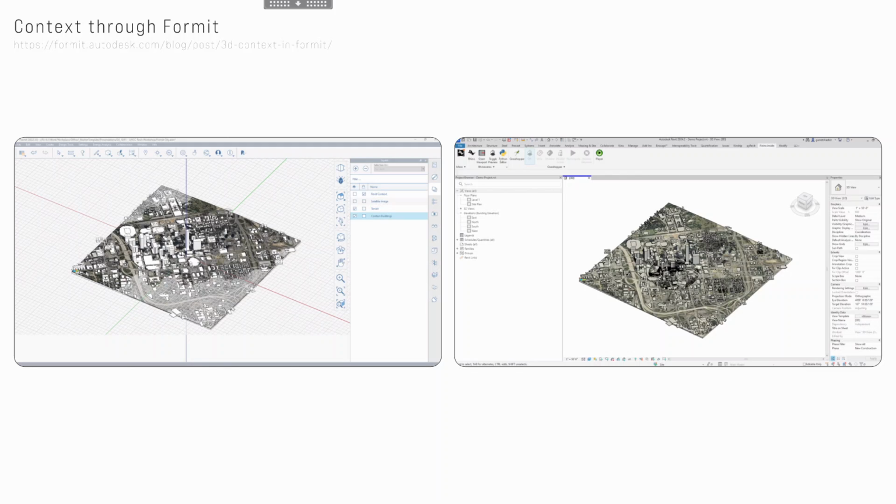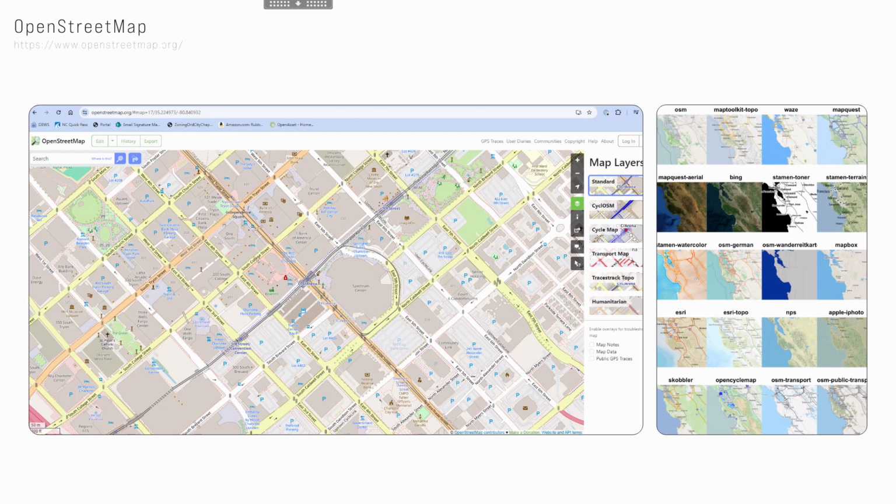And then you can go in and start to manipulate, and I'm sure they probably already have this a little bit, but start to detail the buildings that are actually adjacent to your property, and then use the rest as just background massing. And then you can import that directly into the Revit environment. Again, you can get terrain, but I wouldn't necessarily trust it, especially for site specific. And then there's OpenStreetMap, a really good resource.